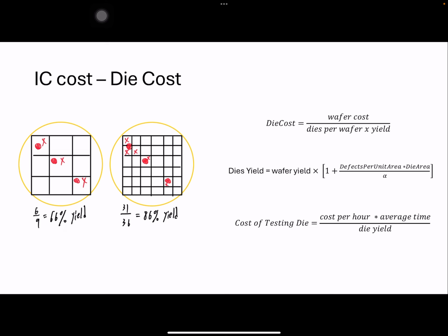But why do people want the chips to become smaller? And what's the difference between 2 nanometer and 3 nanometer? The main point we want the chip smaller is money. When the chips are more tiny, the yield is bigger because the factory has many impurities. Even if we already prevent the dust or other things from flying into the factory, there are still some of them that will affect the chips. We can see the picture in the slide.